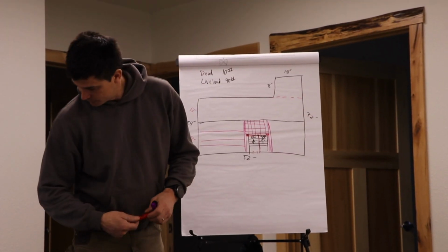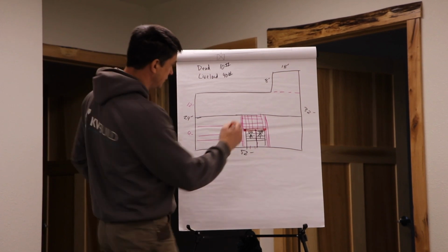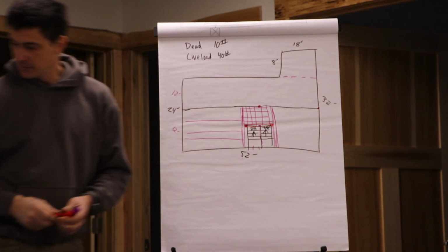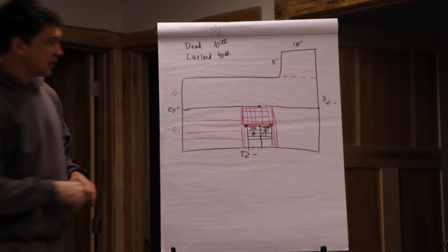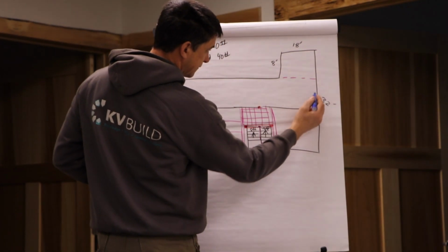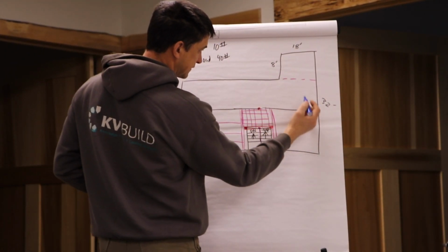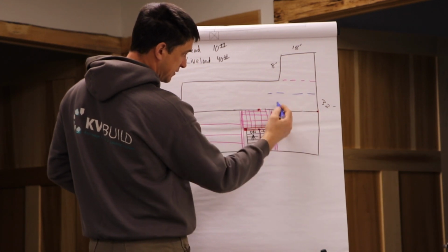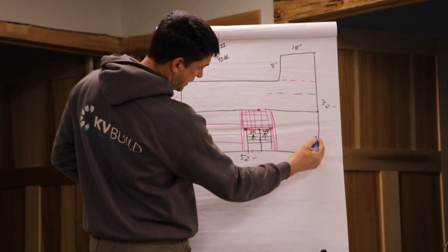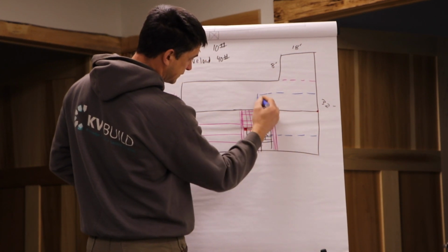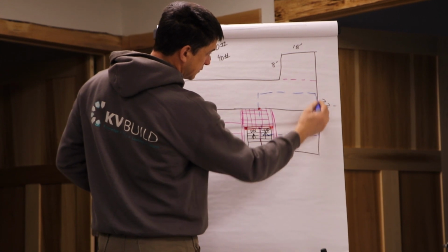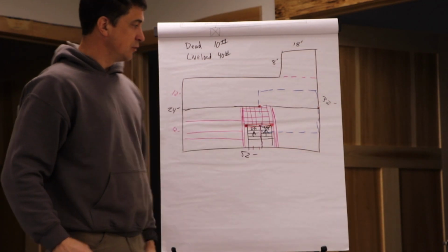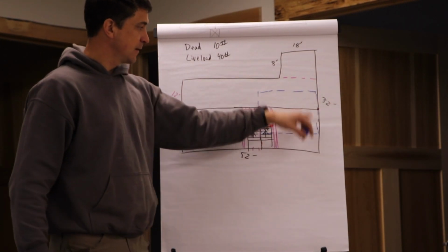So the one load point is right here, the other is there. So that means we're going to have an area that's loading that because the roof trusses are going like this. So there'd have to be another beam there. But for this one, we've got half the span from the middle to that way, half the span this way. So our load on this beam, and thus on our two load points, is this area. Okay? What do we have?